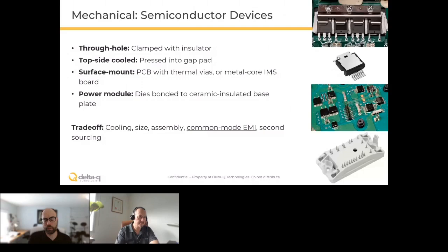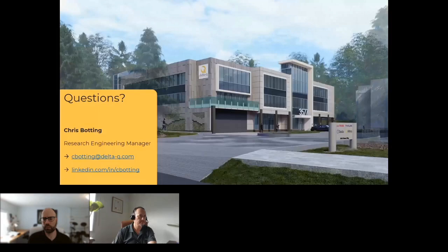Okay, I think we got 2 minutes left. Do you think you could answer one more in 1 minute for a bidirectional charger? How would the design be different for a vehicle to grid versus vehicle to load? Yeah, so the hardware isn't necessarily all that different. Probably still a bidirectional charger, PFC, and a DC-DC converter. The differences may be more in the control and the regulatory certifications.